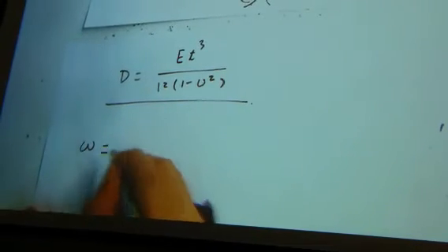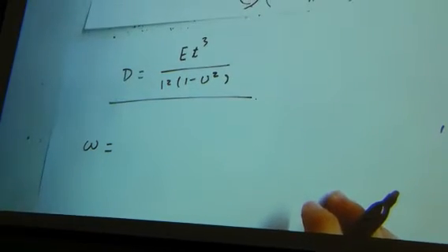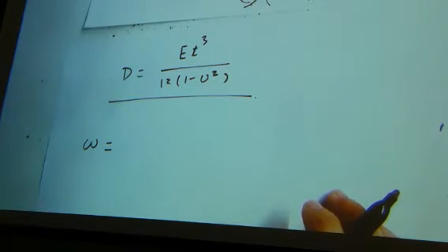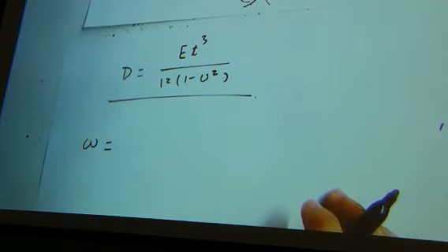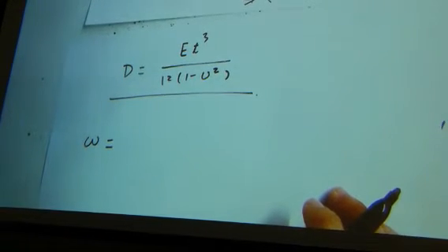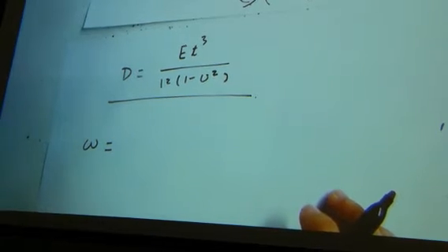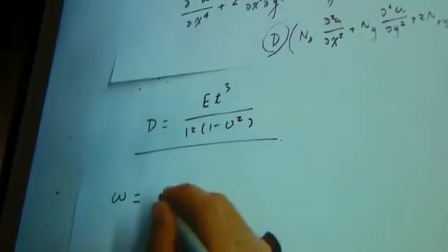And if we make some assumptions, we will assume the shape of the buckling mode. In the homework, I'm asking you to plot the first, second, and third order buckling modes. So you will see this deformed shape follows a sine wave or cosine wave shape. That is from an analytical assumption. We are assuming the deformed shape follows a function like this.